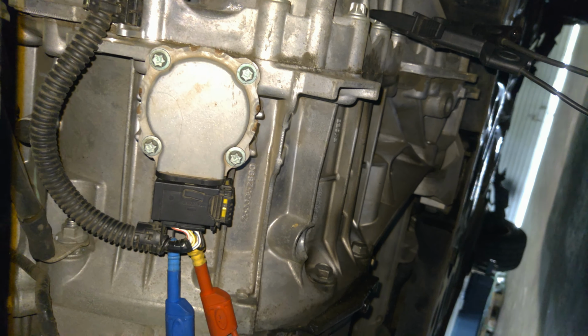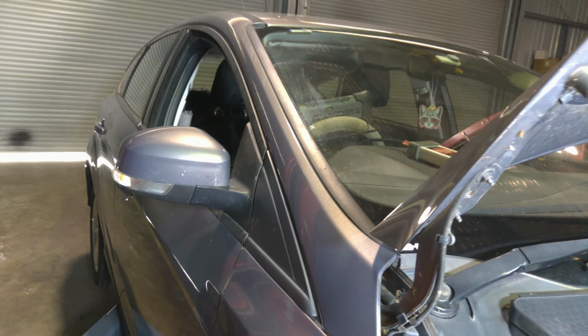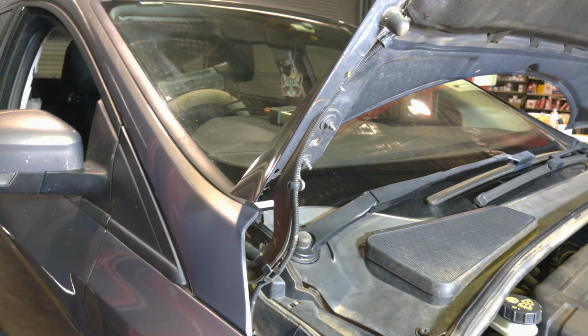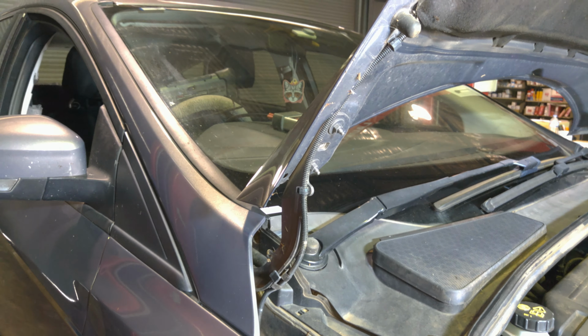Alright guys, I did swap the actuators. Did the same test, drive, reverse, and it didn't make a difference. The signal stayed the same on the scope, nothing changed. So I don't think there's anything wrong with the actuator, but if you don't have all the equipment to test it out, that's something you can do. If you get a fault code saying actuator A or B is faulty, you can swap them out and see if you get different gears.